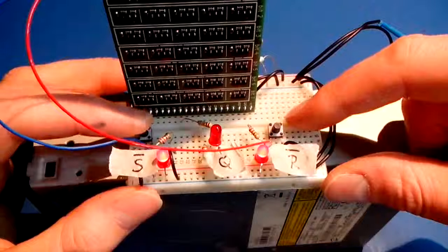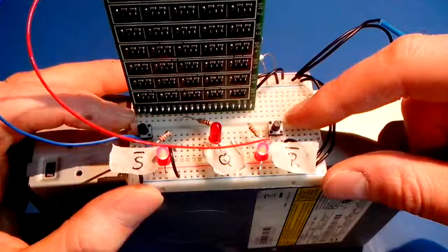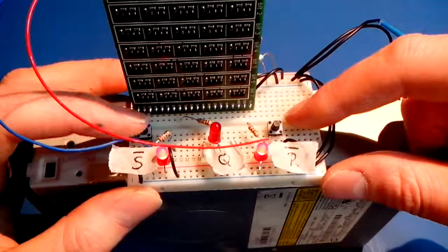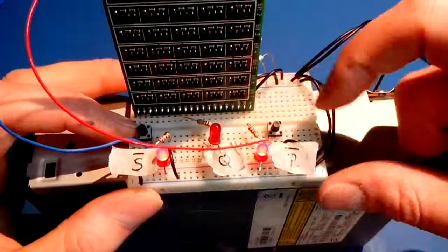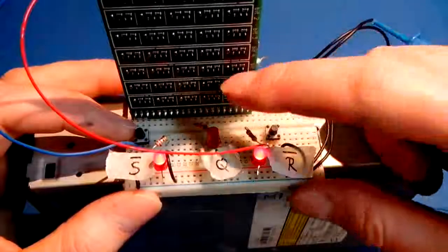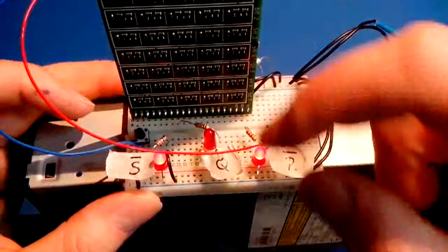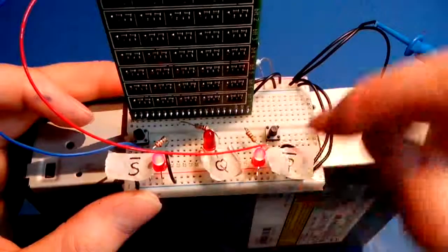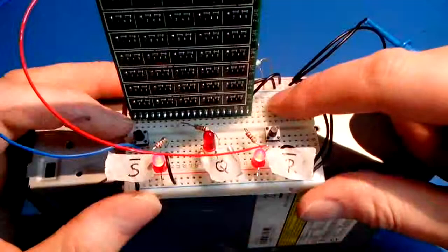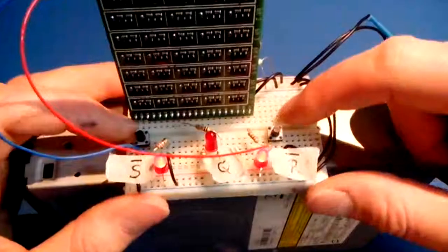Another input S over bar can be controlled by this push button. Pushing the button will activate the set reset over bar input. In other words, will apply a low voltage. And this was a low active input, so it will activate the input. So the middle LED is the output Q of the set reset latch. For now we ignore the Q over bar output because it's simply the inverse of this output. So if we apply right now the voltage, the S over bar and R over bar inputs are 1 as indicated by the LEDs. So now the output of the set reset latch doesn't change state.